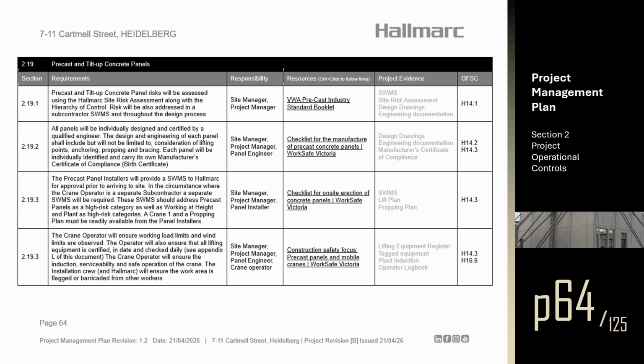Section 2.19. Precast and tilt-up concrete panels. Section 2.19.1. Precast and tilt-up concrete panel risks will be assessed using the Hallmarc Site Risk Assessment along with the hierarchy of control. Risk will also be addressed in a subcontractor SWMS and throughout the design process. Section 2.19.2. All panels will be individually designed and certified by a qualified engineer.